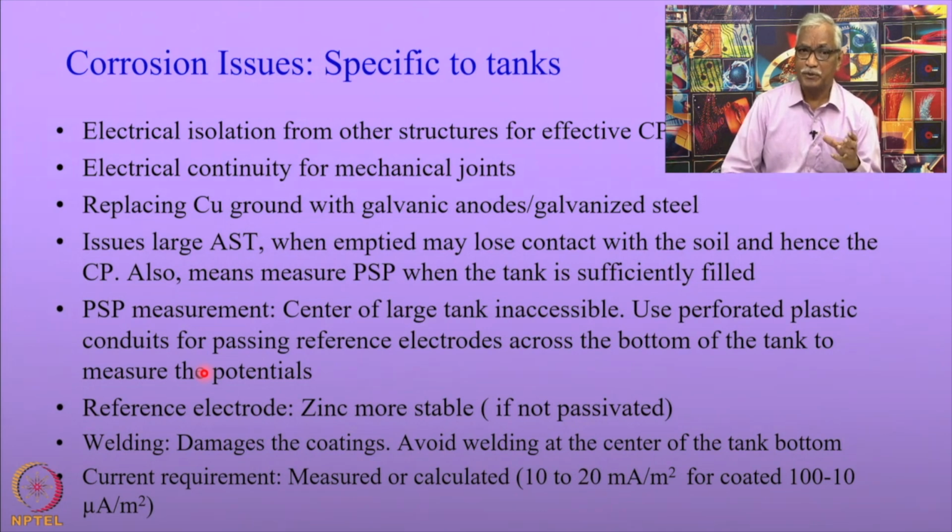It is also possible to use zinc electrodes, because zinc electrodes are just buried in the soil. The normal reference electrodes like copper sulfate or silver chloride have solutions, and they dry up over a time period. So, these electrodes become damaged, they do not show the values, and there is a need to change them with time, which is not possible in the case of tank bottoms.